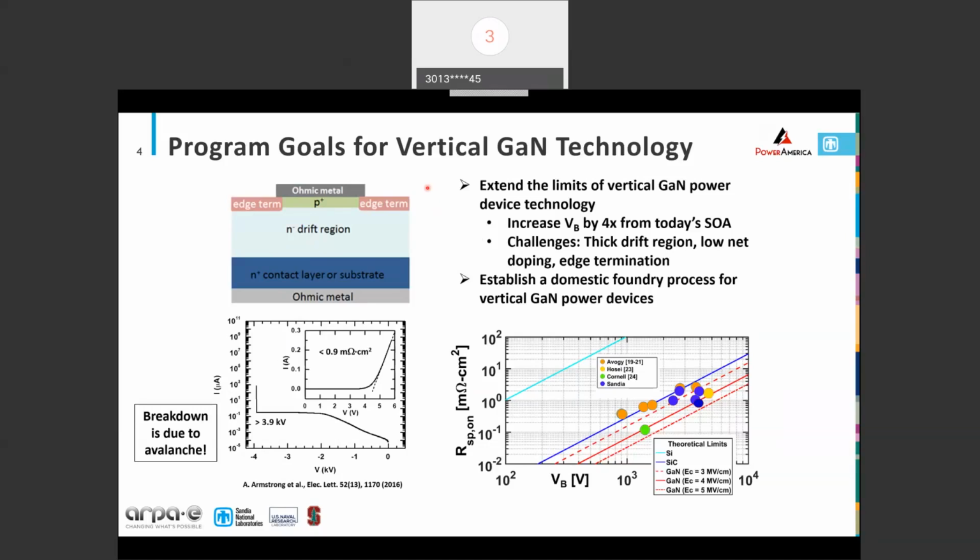So the things you need to think about for thermal management are more similar, I would say, to what you'd have in a silicon carbide vertical diode. Of course, it's a different material and slightly different thermal conductivity, and there's variation between P and N type and so forth. But it's not as interface intensive a device as a HEMT. So you won't have those bottlenecks at those interfaces.